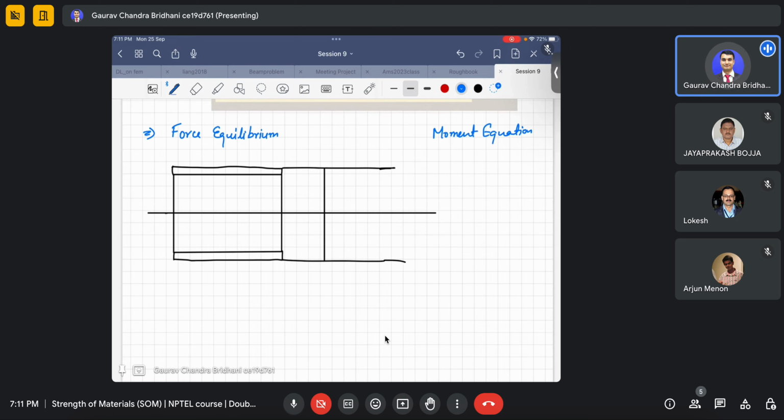Okay, and you have seen in the lecture also how the professor has shown the strain varies. Even in the sandwich beam, there won't be any disturbance at the surface where the two materials are joined. It will be continuous, because to ensure the compatibility. So there should be compatibility between the two. On the surface of this plastic and the aluminum, the two are attached very perfectly. So strain varies linearly. Okay, so this is our strain profile epsilon.